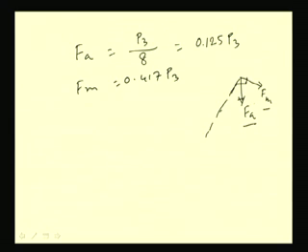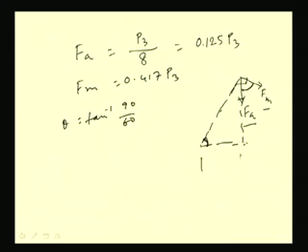Now, we can find out the resultant. To find the resultant we have to know the angle. So, theta will become tan inverse of 90 by 60, because this distance is 60 and here one rivet at 30 and this is 60, so total is 90.